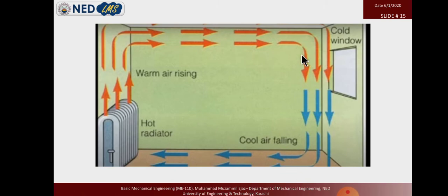So we have a temperature difference: anything kept on the top side has a higher temperature, and anything kept on the lower side has a lower temperature. We don't want this in the fridge. So we place the cooling plate on the top side of the fridge. So we have a natural convection flow and a uniform temperature throughout the fridge or any room.